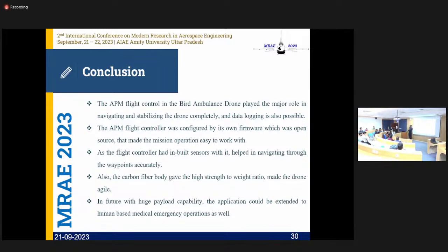Yes, we can. That is called altitude hold mode. There is a mode in Mission Planner called altitude hold mode. And one more mode: once the drone has gone to that place and it has to come back to you, you need not give the location again. You have to select the option called return to home. From where the drone has started, it will come back automatically to you. We have tested this on our football ground only.